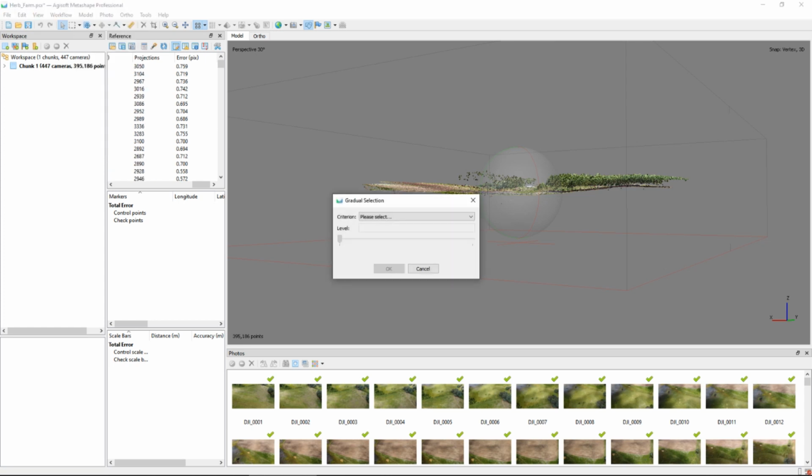Once that step is complete, we'll choose our third option. From the drop-down menu, we want the bottom selection. This time we want to attempt to achieve about 10% of the active tie points. Observe again in the bottom left of the window as we move the slider bar how the selected number of points changes. Target more or less 10% of the points, select the result, accept it, delete those points, and for the last time we will optimize those camera parameters.